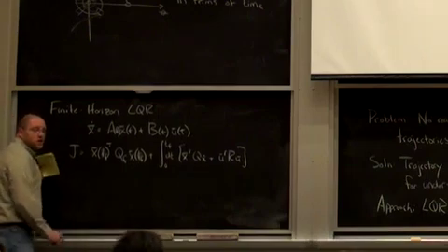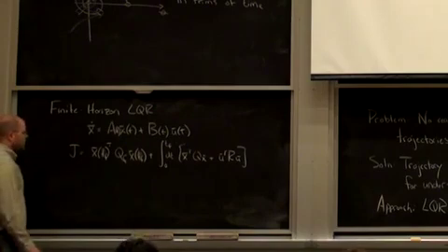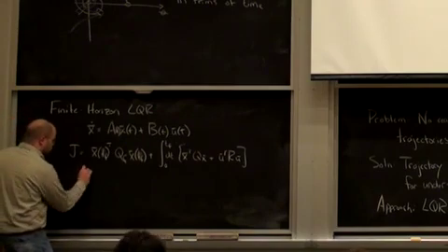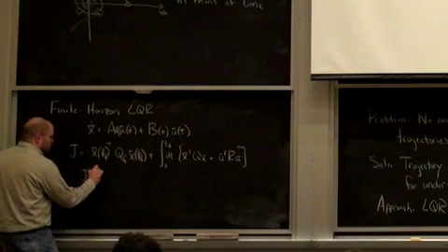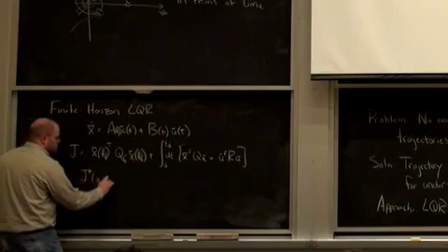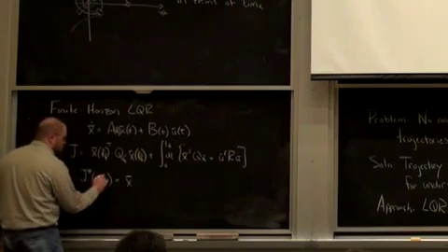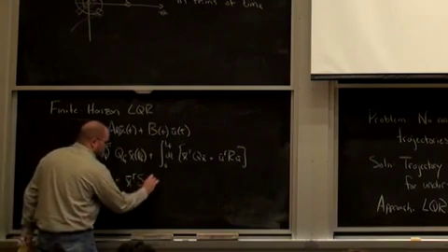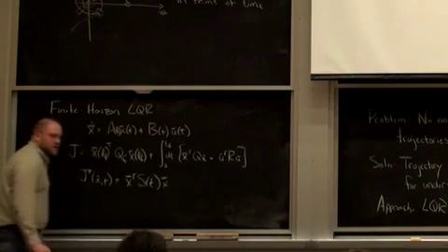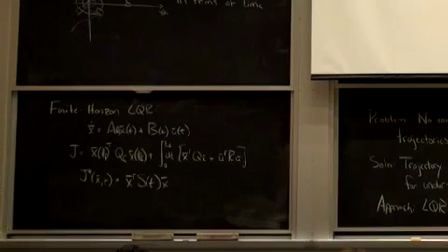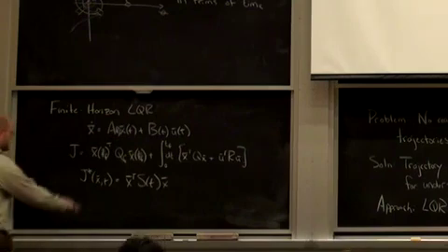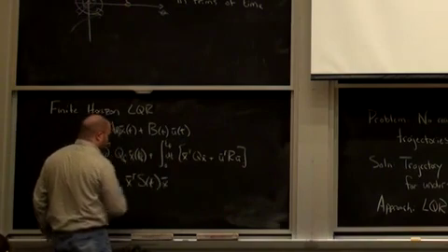Okay, in the original LQR derivation, we guessed that the optimal policy had the form u bar equals negative K of t x bar, with the cost to go being x bar transpose S of t x bar. That's still intact. That's still a good assumption. This thing is linear. It's just in a different coordinate system.